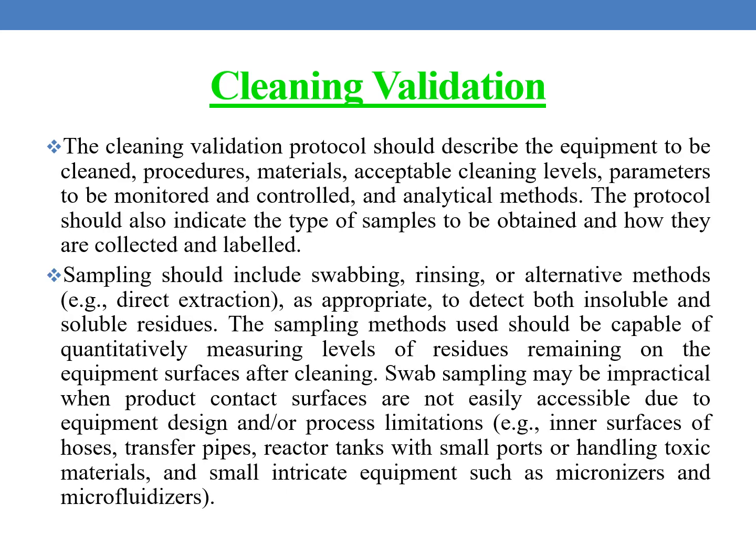The cleaning validation protocol should describe the equipment to be cleaned, procedures, materials, acceptable cleaning levels, parameters to be monitored and controlled, and analytical methods. The protocol should also indicate the type of samples to be obtained and how they are collected and labeled. Sampling should include swabbing, rinsing, or alternative methods, for example, direct extraction as appropriate, to detect both insoluble and soluble residues.